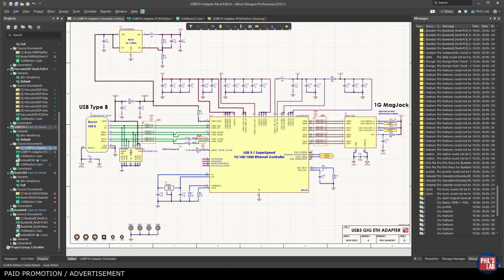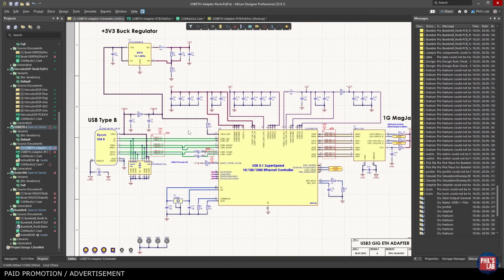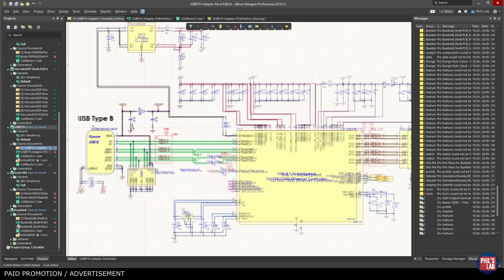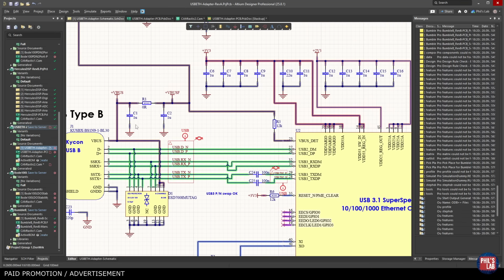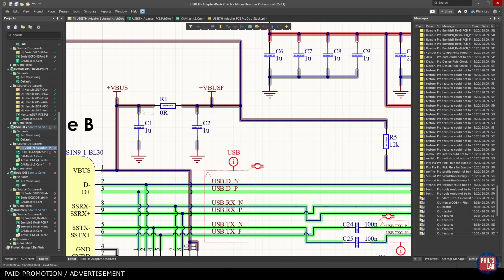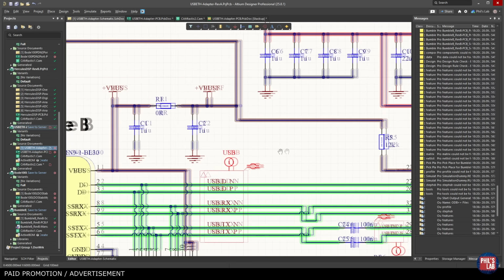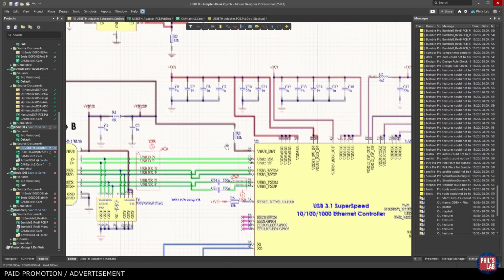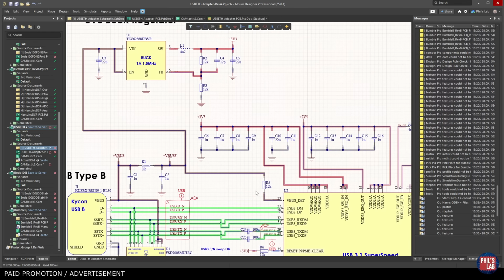Other than net names, it's also incredibly important that you have proper component designators in place, that you don't have any duplicate designators. Every item is unique and sensibly annotated. This is important because this information, for example, that this capacitor is designated C1 or this resistor is R5, will be included in the ODB++ export that will then be used in HyperLynx to assign, for instance, certain models to capacitors or voltage regulator modules and so on. So make sure your components are properly annotated and designated.